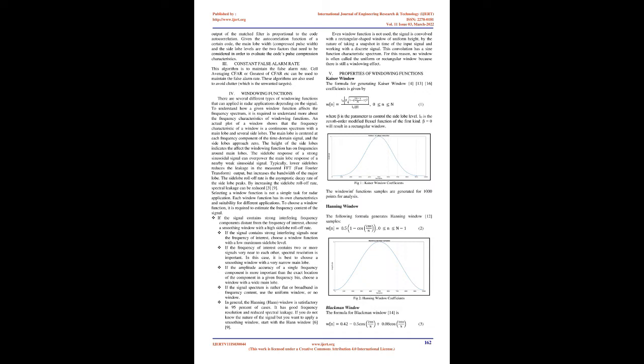The pulse compression is a practical implementation of a matched filter system. The coded signal may be represented either as a frequency response H(f), or as an impulse time response h(t), of a coding filter. The coded signal is obtained by exciting the coding filter H(f) with a unit impulse.